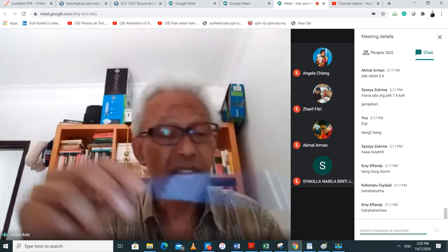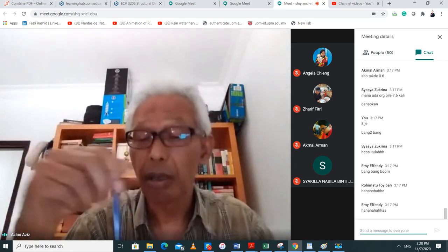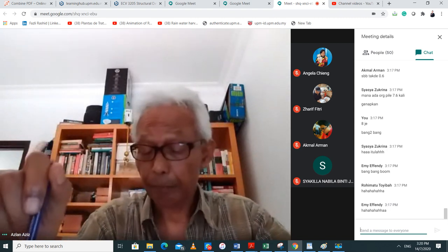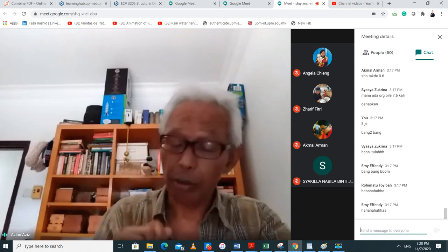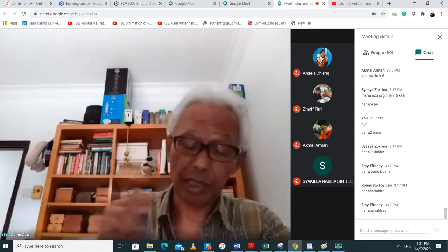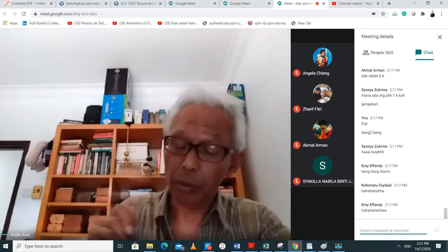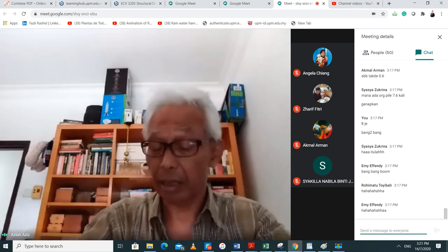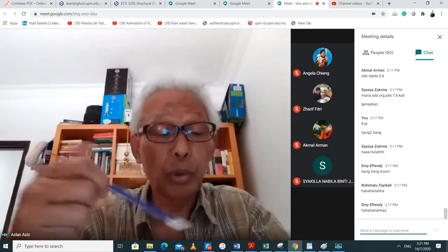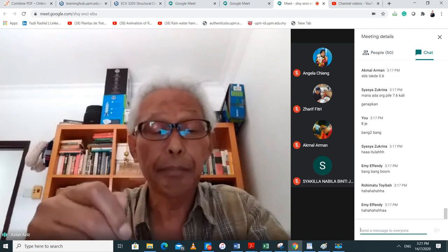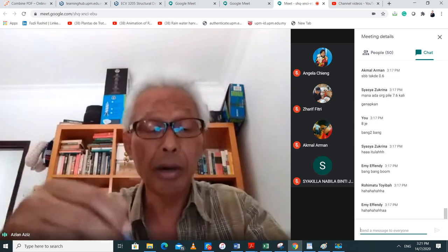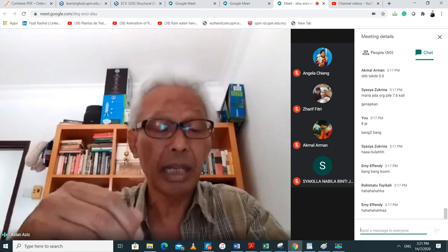this business just now, a few minutes ago, if you refer to the previous page. You remember we said the ultimate compressive load is 1625 kilonewton. I'm on page 347. The ultimate uplift load, 2.5, is 563 kilonewton. So if you look at this here, A sub B plus A sub S F sub S, you notice that above 1625, there is no problem.